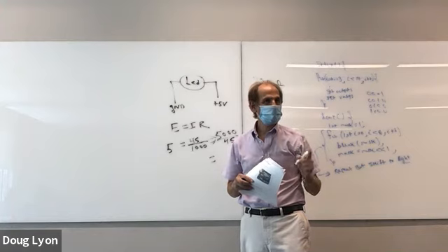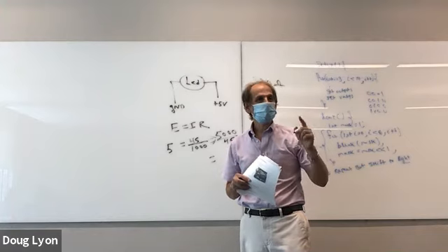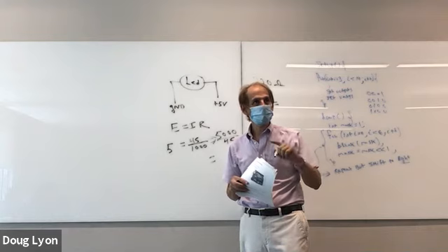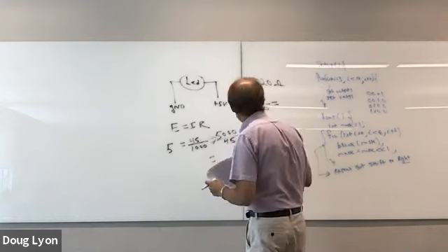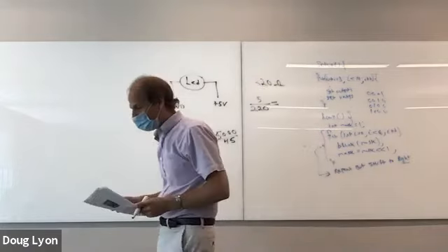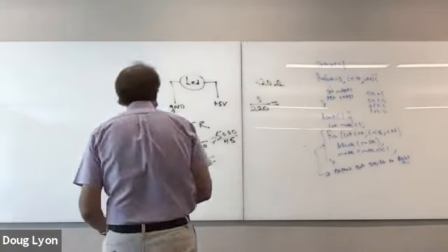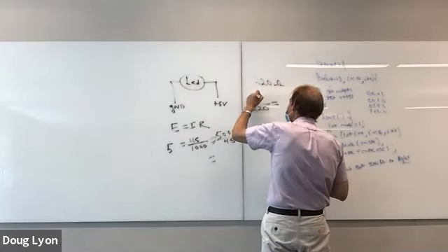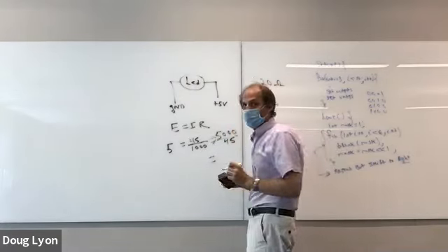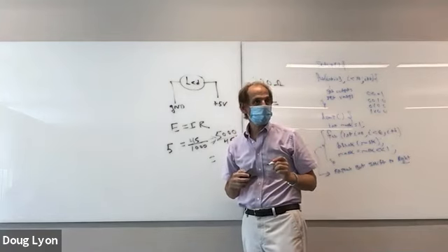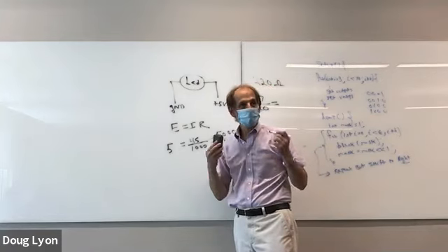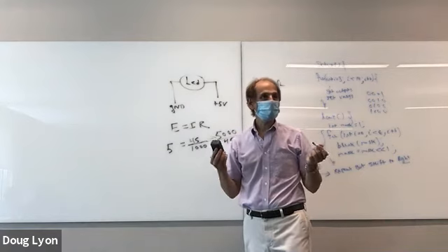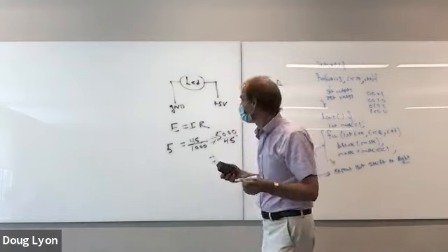But it's not quite the same, right? Because why? There's a 7/10 of a volt drop on the LED. So in fact, it's not really 5 volts that will be the drop. The drop will be something like 5 minus 0.7, which is equal to 4.3. So if I take 4.3 and divide it by 220, that's probably closer to my current limitation for the LED.